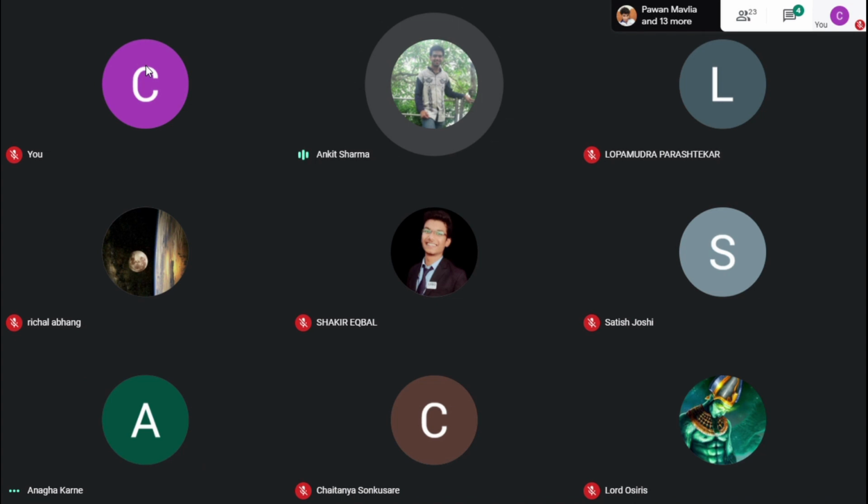Okay. And antennas, ma'am, because we need different frequency ranges. Since I said it's a multi-purpose setup, we are designing around 5 antennas which we'll be working with. Three of them will be omnidirectional and one of them will be directional, and I guess two of them will be, one for our geostationary satellites and one for our radio astronomy purposes. Okay, fine. So the same setup can be used for all these multiple antennas; you just have to change the antennas for different frequency receptions, basically.